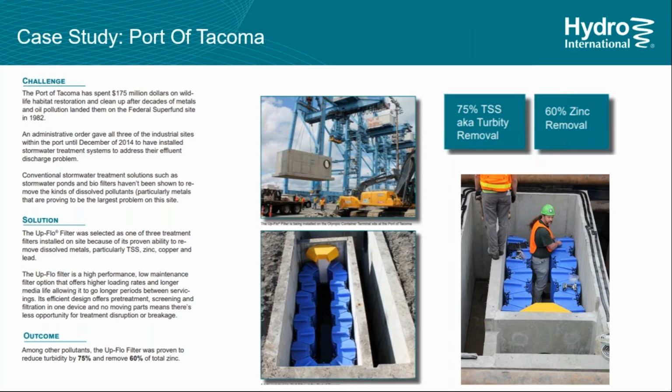When you are specifying an Up-Flo filter, all of the internal components will be installed at the precast facility, so that when it gets to site, the contractor is only responsible for grouting the pipes and bringing it to grade. Now, the last reason, which will bring us into the future of stormwater, why the Port of Tacoma chose the Up-Flo filter, was on the monitoring and the data analysis that comes with it.